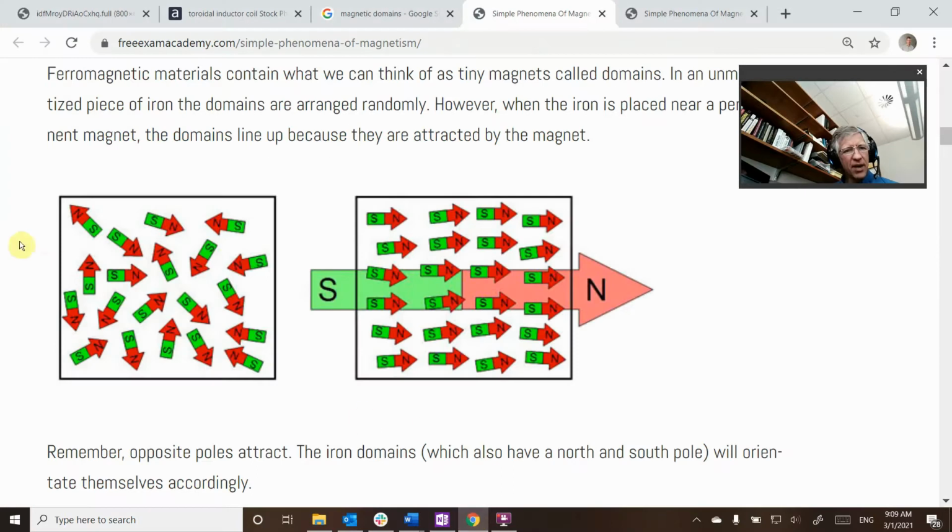What ends up happening is that a magnetic material is built up of a bunch of these little magnets, which are called little domains. And as you apply a magnetic field across there, all these magnetic domains are going to align. When all of them are aligned, then increasing the strength of this magnetic field can't align any more, and that's going to be my saturation effect. And how easy it is to align these domains is your permeability, which is that mu.